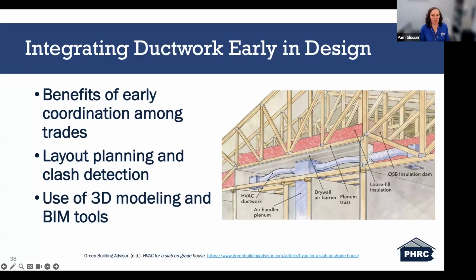So the image that I put on here, speaking about designing early, is an example of ductwork that's integrated within a truss system. You can also get it integrated in a floor system, possibly too. So that's keeping all of your ductwork inside that conditioned space. You're not dropping any ceilings or building any soffits. You're putting it up into the truss as well. So, as I stated before, early planning leads to better performance, easier installation, and improved code compliance for the system as well.